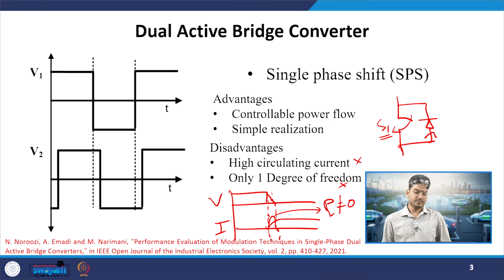So, as our switching frequency is very high, the switching losses of these circuits will be dominating over here. Okay. So, the maximum part will be contributed from the switching loss in the circuit. So, if I am able to go for soft switching, I will be able to increase the efficiency of the circuit. Okay. So, ZVS range will also be dependent on the control technique which we are using. Here we do not have any flexibility or any degree of freedom left with us to improve our ZVS operation range or to expand our ZVS operation principle. Okay. So, this is the requirement of our degrees of freedom. So, we have seen three such requirements.